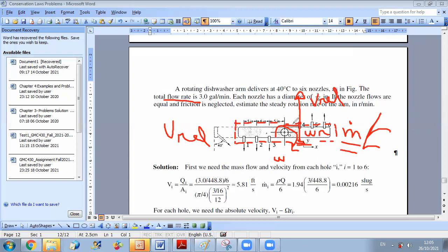So please don't confuse two things. The rod system is rotating, but the control volume enclosing it is fixed. At any instant, the control volume considered is just a fixed control volume crossing the inlets and outlets of your rotating system.